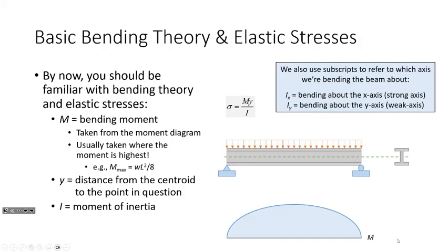Now, the next thing that you need in order to compute bending stresses are some properties of the cross-section, right? The I shape, as it were, has numerical properties that define how it is going to withstand bending stresses and shear stresses, etc. And the most fundamental property that we need is a moment of inertia. Okay? And in Engineering 216, I taught y'all how to compute a moment of inertia. We're going to go back to that a little bit today.